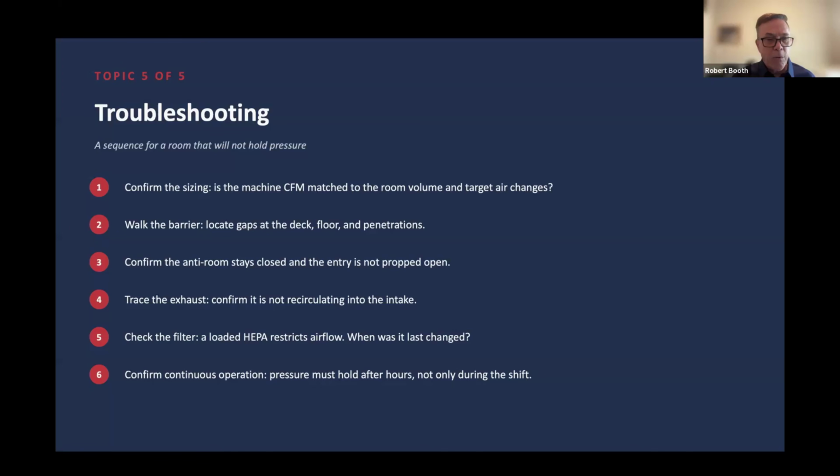Yeah, it's our rank order, and this is one thing that we preach when we're doing education. The rank order for negative pressurization machine placement is one, outdoors, away from an outside air intake. The second is if you're going to go outside and there's an air intake or a door or something, HEPA filter it.